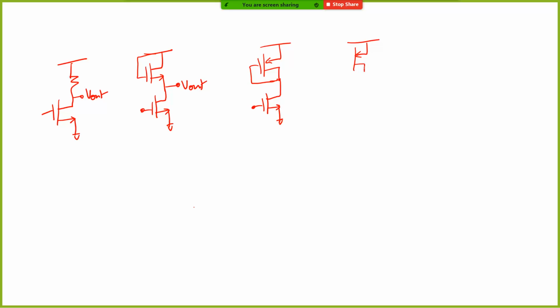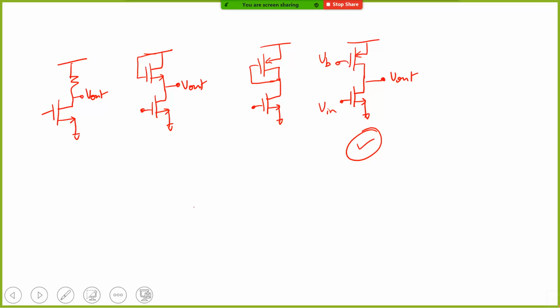And then we moved on to what is called the common source with the current source load, right? In fact, this is one of the most commonly used topologies for common source. And today we will look at a few more variants as well before moving into the common gate amplifier. One extension you can see here is that in all these cases, all the transistors have to be in the saturation region.